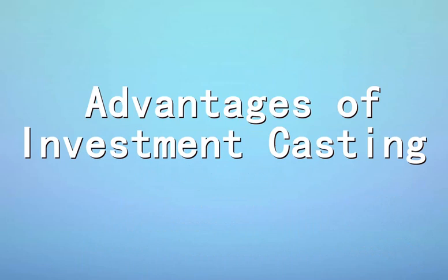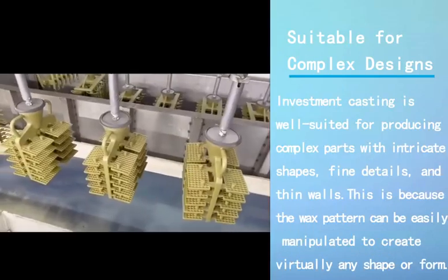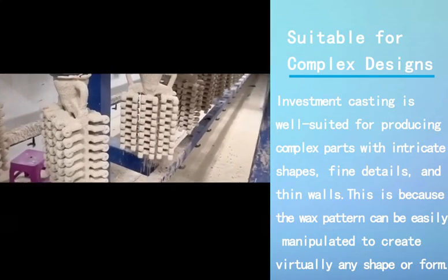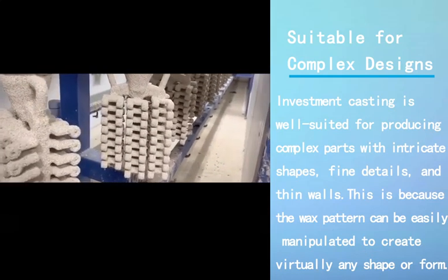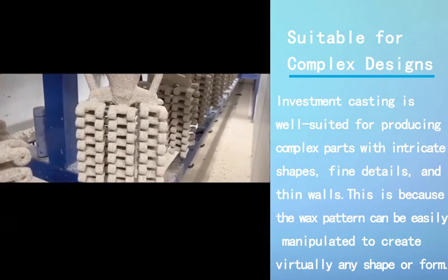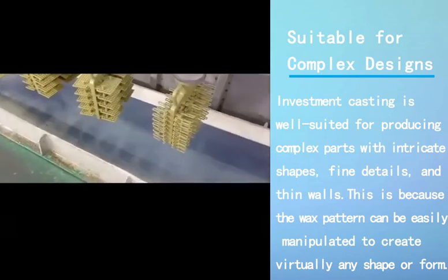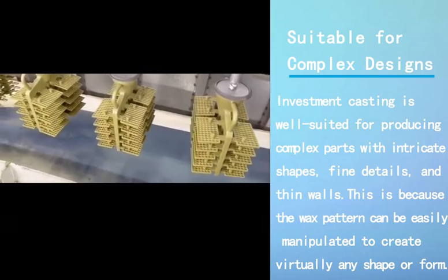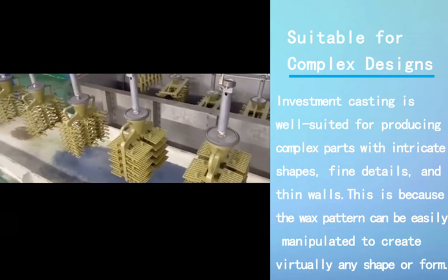Advantages of investment casting. Suitable for complex designs. Investment casting is well suited for producing complex parts with intricate shapes, fine details, and thin walls. This is because the wax pattern can be easily manipulated to create virtually any shape or form.